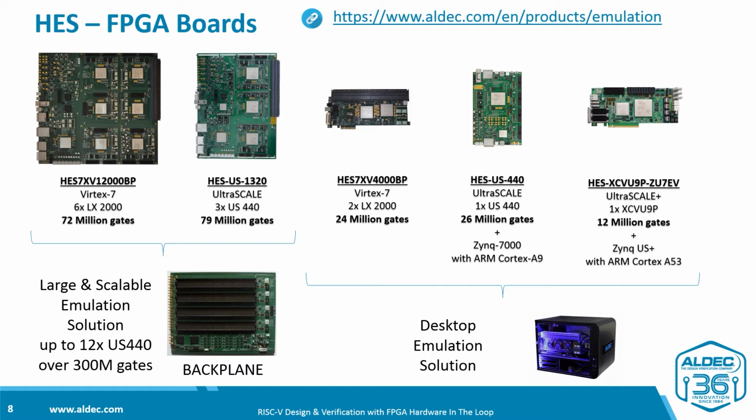Single and dual FPGA boards are often used as desktop emulation for block-level verification, but also for system level if used in co-emulation with virtual platforms. Desktop emulation is cost effective, so it can be replicated and shared across the corporate network, and that provides convenient access to many hardware and software developers.